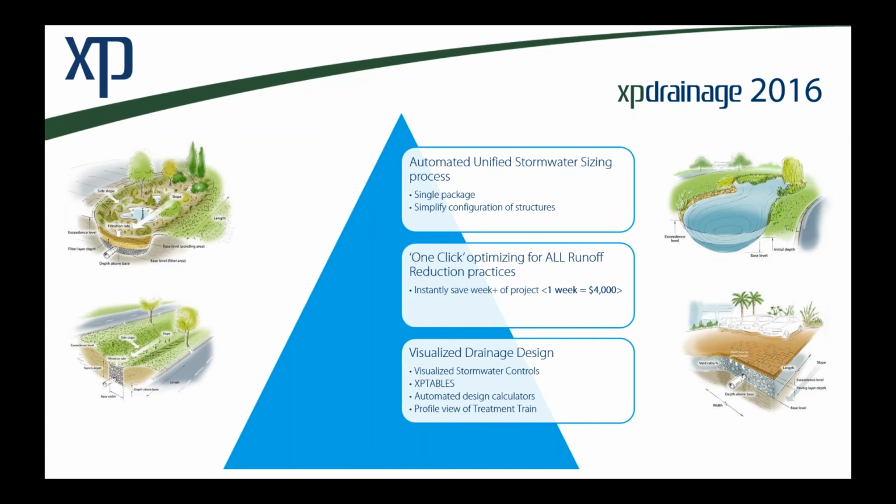We still need a human brain to look at how we can, in a sophisticated and elegant way, account for those higher flooding events. That begins to get pretty complex. So runoff reduction sizing is pretty straightforward, pretty easy. Let's make that even quicker to implement so we can get on to the really complex items. That's what we're going to do with that automated sizing.